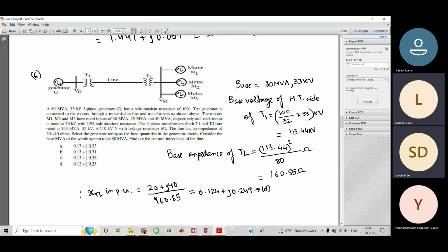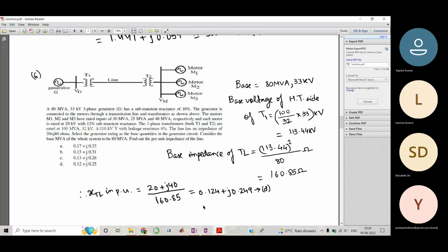Yeah, it is clear. I just have a question. In case of transformers, we are representing the transformer impedances in percentage. Is there any practice to represent the line value also in percentage? In the transformer, I can understand the reference values are taken as its own rating, its own MVA and its own voltage, and the manufacturer represents the value in a percentage, and we are converting it into a new base based on our SLD and voltage levels. What about the transmission line? Will they only mention it in terms of R plus JX generally?